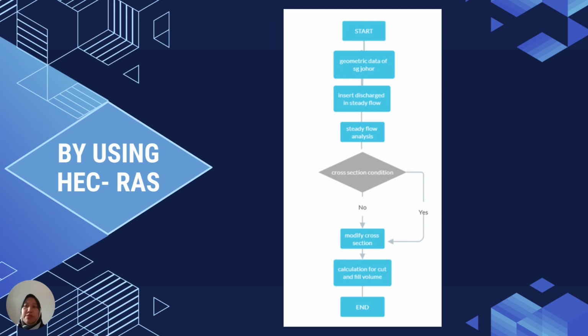So, by using HEC-RAS, firstly the project starts by considering the channel geometry. After importing the data into the HEC-RAS project, click View/Edit Geometric Data and it shows that the river reaches the network from channel 0 downstream until channel 1477.5 for upstream. Based on the information given from the discharge, the channel was designed based on 5, 20 and 50 years. Various adjustments and modifications have been made to the model to avoid the flood from occurring.